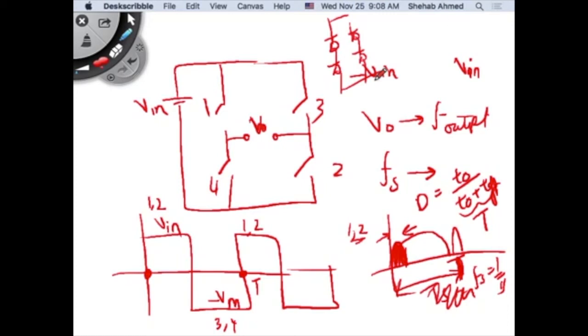But yeah, you can take this inverter and supply an AC load, and no problem, it will work. And the benefit here is I'm switching at a very low frequency, so my turn on and turn off switching losses are very low, and I'm supplying an AC waveform. It's great, but I have a lot of harmonic content, right? The alternative is to figure out a way to improve the harmonics. If you want to create a nice sine wave, you have to figure out a way to create the sine wave, and it's not going to be by switching at fundamental frequency anymore.